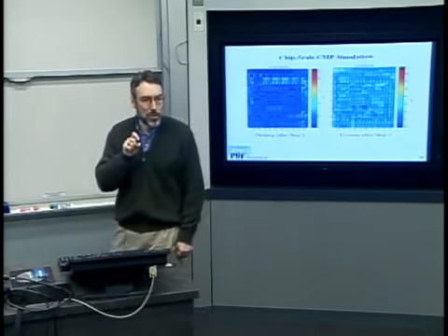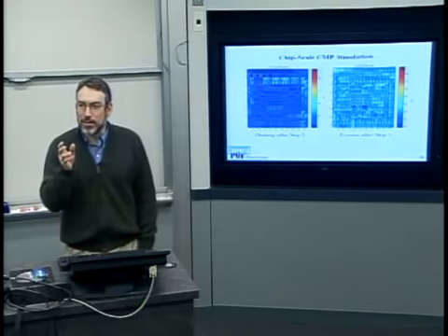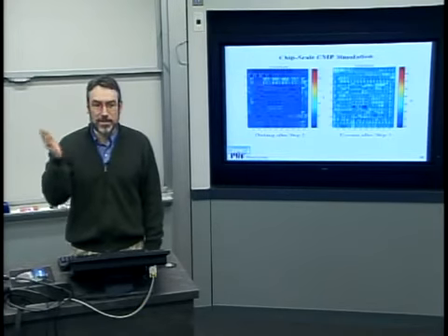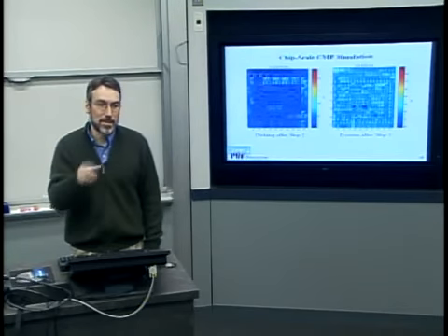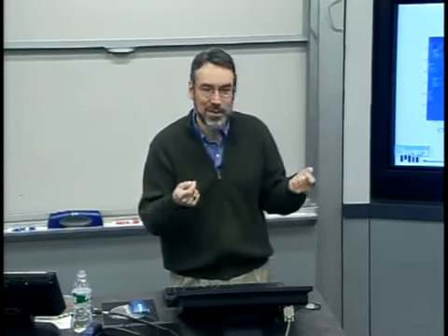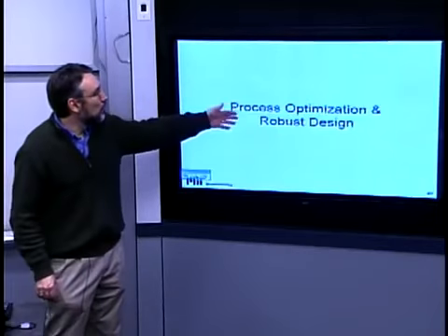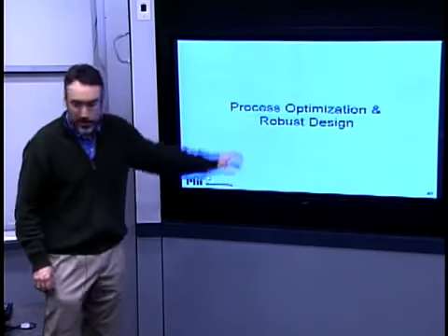And that could be very important because the thickness of a copper wire determines its electrical resistance. It even affects the coupling capacitance between two neighbor wires. So those key electrical parameters, resistance, capacitance, that determine interconnect speed depend on that critically. So that linkage with robust design can be very important.